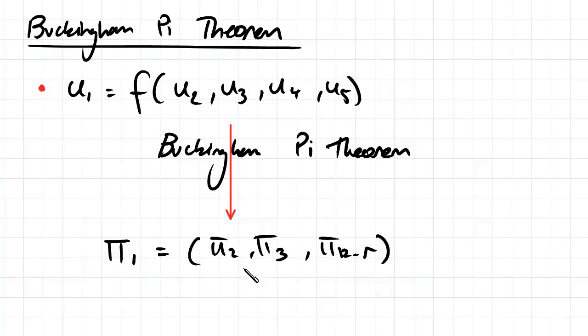Now, in this course, we'll have a number of known dimensionless pi groups, but using the Buckingham pi theorem, we were able to produce our own dimensionless pi groups, and sometimes we got pi groups that we already knew, like, for example, Reynolds number or Froude's number are dimensionless pi groups that you can produce. So essentially, you're taking a variable which is a function of a lot of other variables, and you're replacing that as a function of a couple of dimensionless pi groups, and that's really dependent on the number of different variables that we have and the number of reference dimensions we have, and that's in terms of the MLT system.